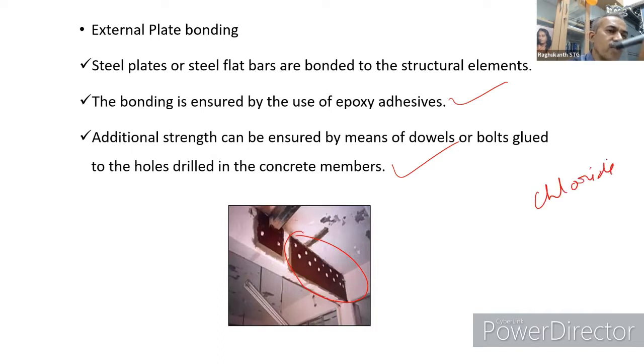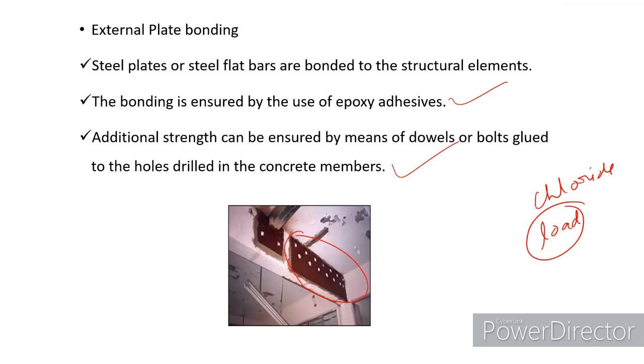The other most important thing is the load. The loads were the most important, because they have been altered, and these buildings were constructed some 40 to 50 years back. The codes also changed, and so many issues are there. All those things we have nicely classified, and we have also suggested what type of repair strategy you have to follow for these beams, columns, slabs, and other elements.